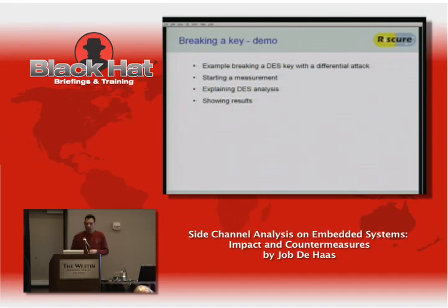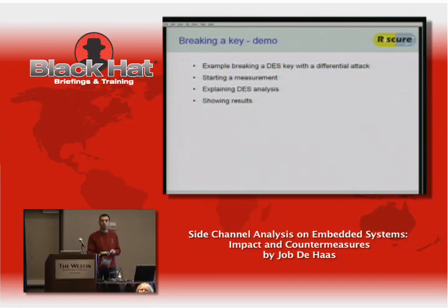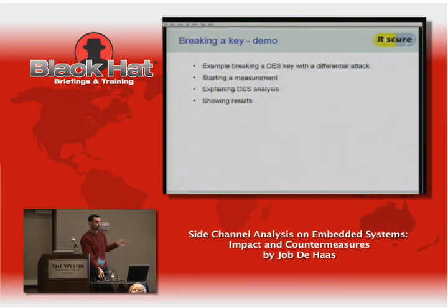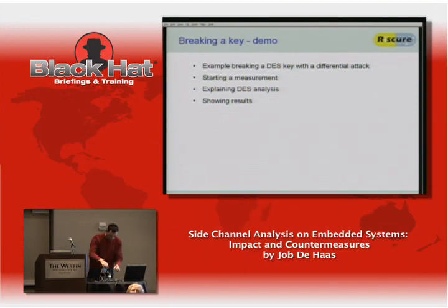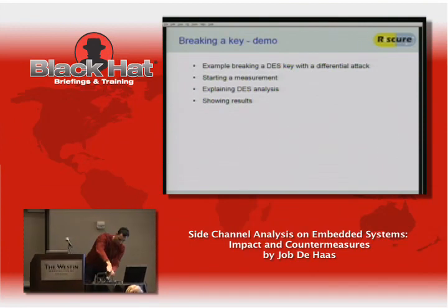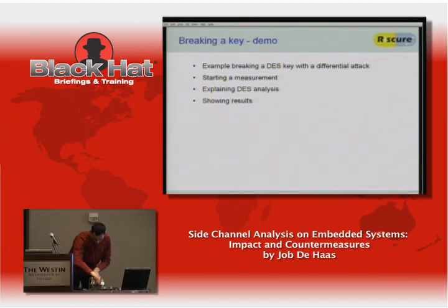Okay, so what I want to show here is how to break a key that's actually on this smart card. So I'm now transitioning to a power measurement setup. I'm using a box that we developed, which is doing that power measurement and tries to have a signal that's conditioned as well as possible, and also supplies the triggering. So similar to the embedded system I have here. I have to start disconnecting some stuff here. Let's see, yes, and then the trigger.